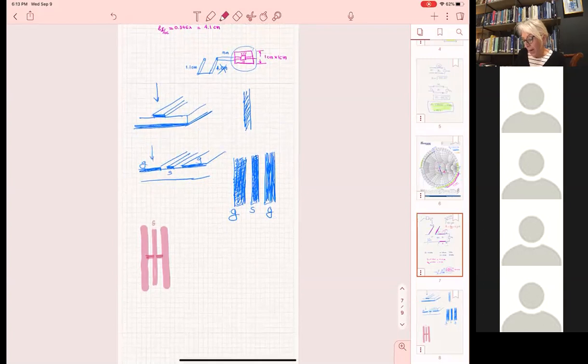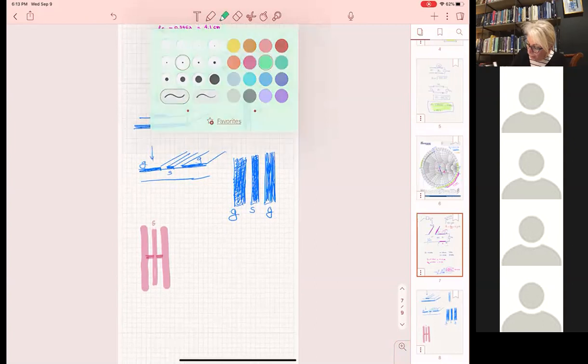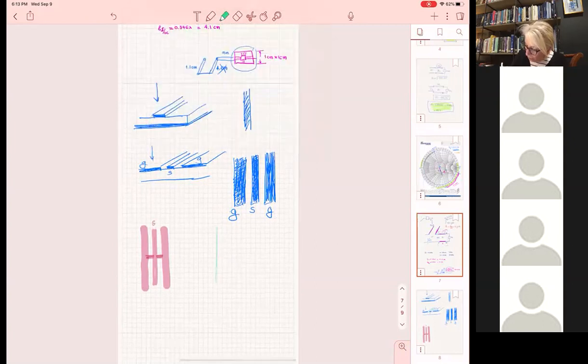Now, what happens with a microstrip? Because you have your conductor on one line, what's easy to do is to create something and leave it open, all right? Because your metal is on the other side. So if I do something like this, it's going to be like a series stub.